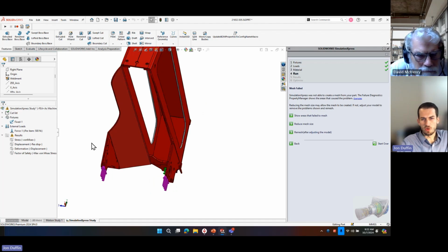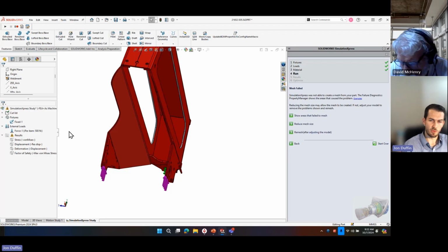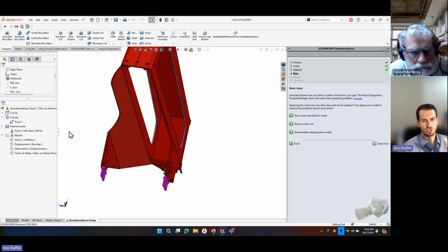Now, one thing to note is that typically in FEA analysis, when you have thin components, you're treating them as what's referred to as shell elements, which means you represent it as a surface with an assigned thickness behind the scenes. The reason is that to really get good results on thin geometry like sheet metal components, you normally need at least two elements going through the thickness of the parts.